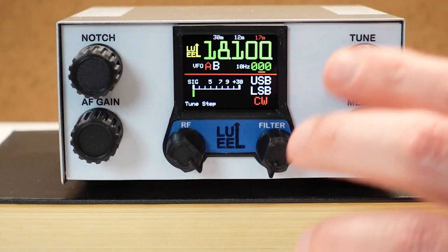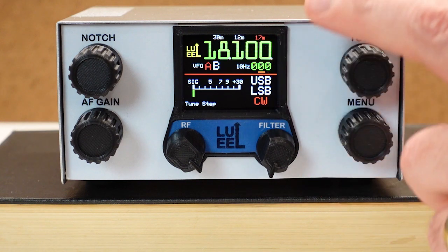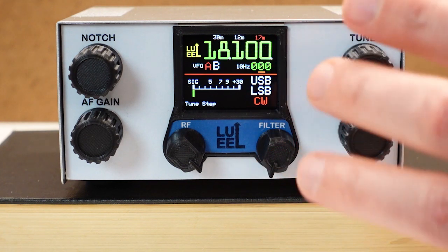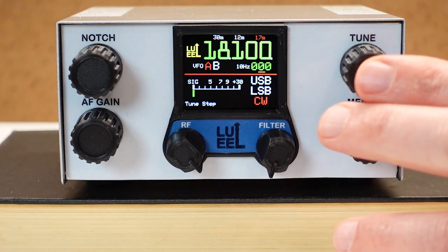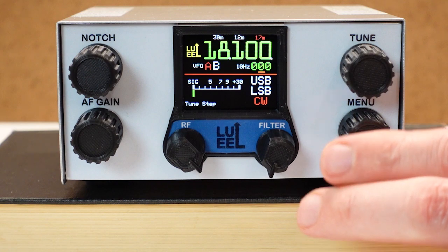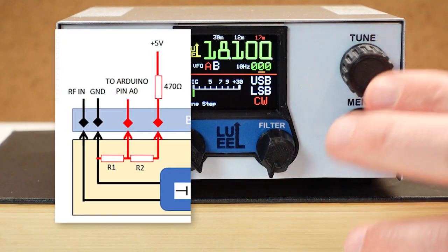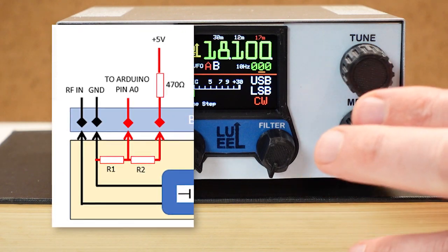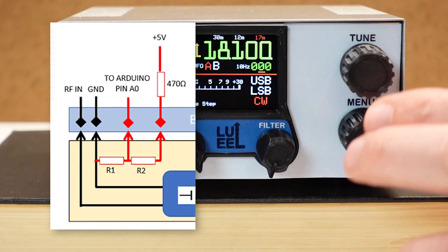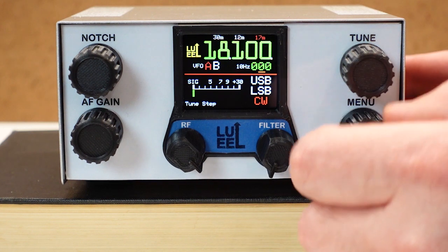So I had off-screen changed the bandpass filters from the 30, the 12, and the 17 meter that were in the receiver the last time it was powered up, and now has the 40, the 20, and the 15 meter filters. So if you recall from a prior episode or two, I showed how I'm using the analog input of the Arduino to detect a simple resistor divider. Then each filter has its own unique voltage output. So in order to set the receiver, so to speak, for the new combination, what I do is go into the menu.